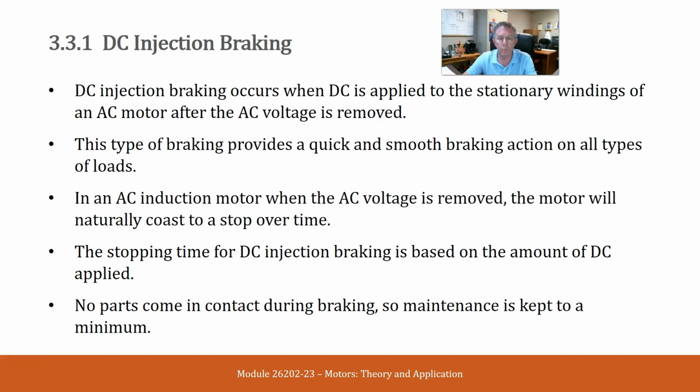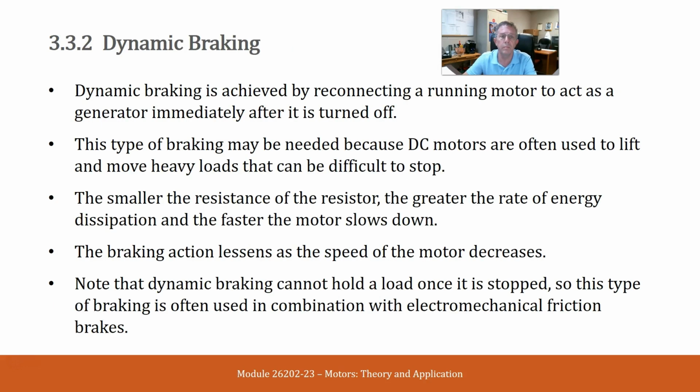In an AC induction motor, when the AC voltage is removed, the motor will naturally coast to a stop over time. The stopping time for DC injection braking is based on the amount of DC applied. No parts come into contact during DC braking, so maintenance is kept to a minimum.